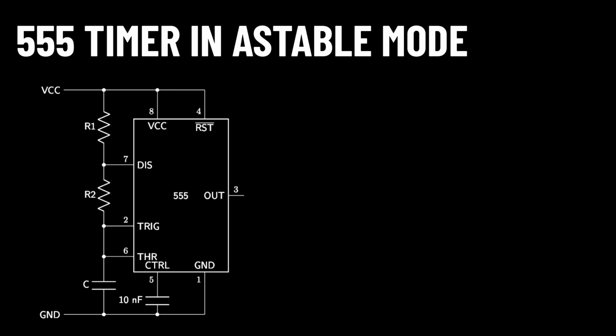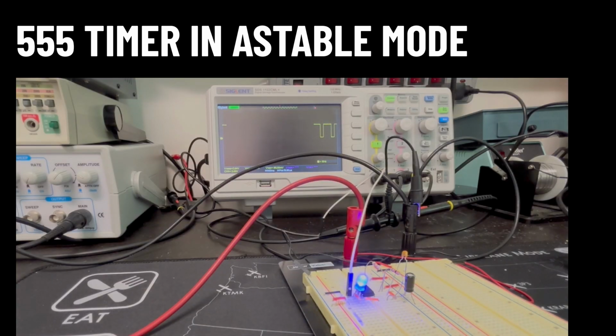The second clock source is a 555 timer used in astable mode. This chip is small, cheap, and relatively straightforward to use after you get the hang of wiring it up. However, sometimes 555 timer chips have some glitchy outputs that may cause issues with your circuit. I see this occur frequently in design projects in this class.